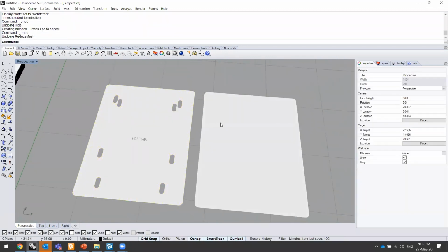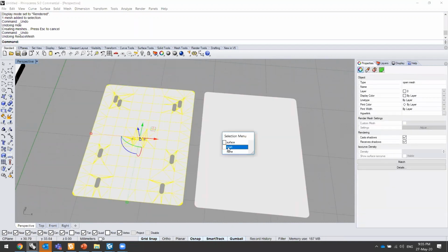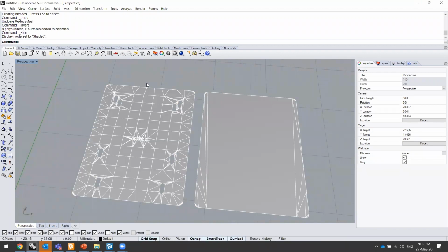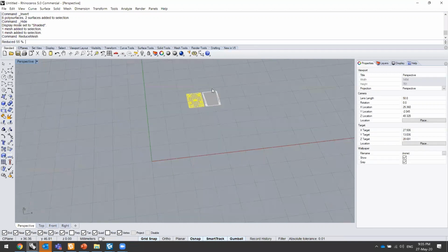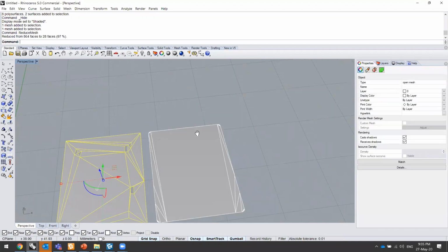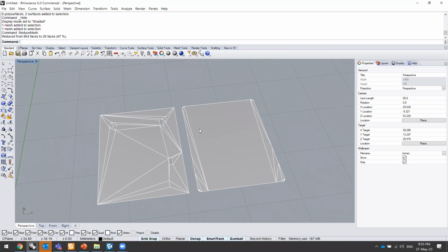So you can imagine the same thing being done in Model Lab when you're reducing the numbers. If you have already well defined what features you would like in your final product, it knows to just put those polygons, those triangles, in where it matters. So in this case, you get drastically different results. Let's reduce this again to 30. You get drastically different results if you were to remove the holes.